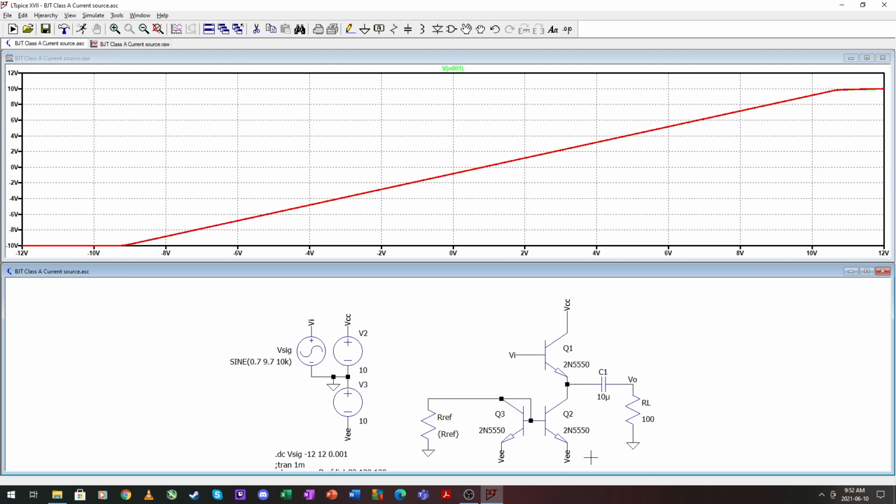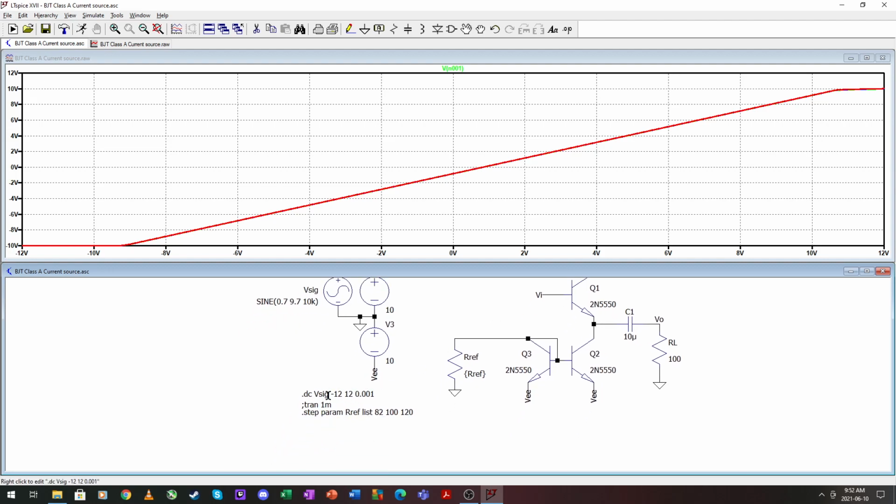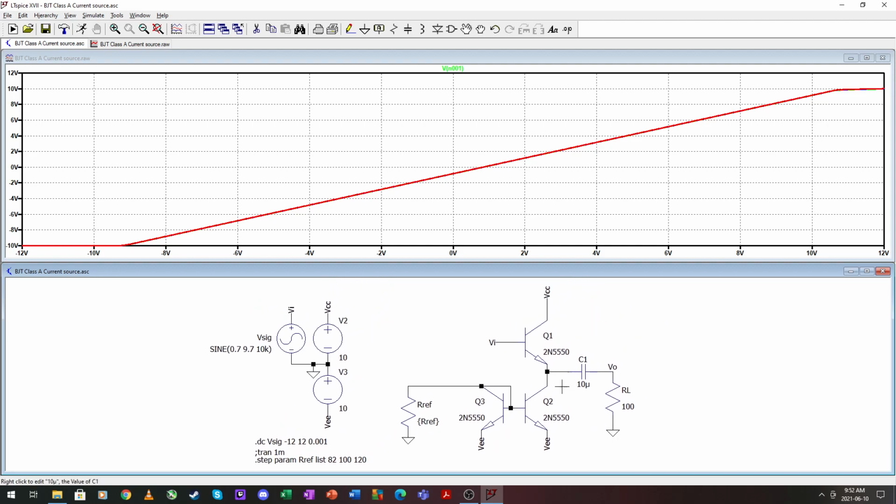You need to measure on this side. If you want to do the DC analysis, you can't measure on that side of the capacitor anymore, because capacitors are DC blocking. So when doing a DC sweep like this, remember to perhaps remove some capacitors if you want to see the effect over to a load resistor or something.